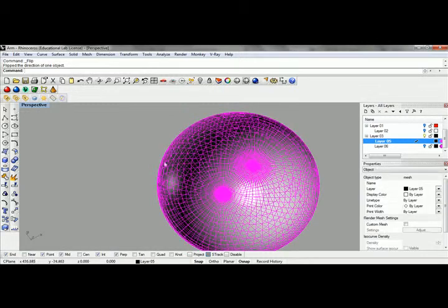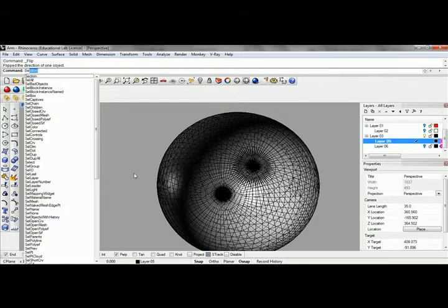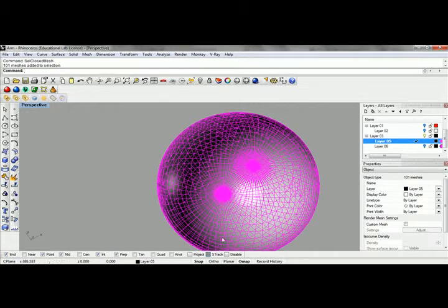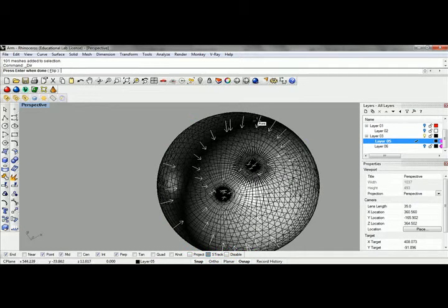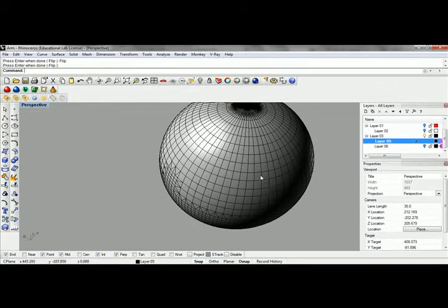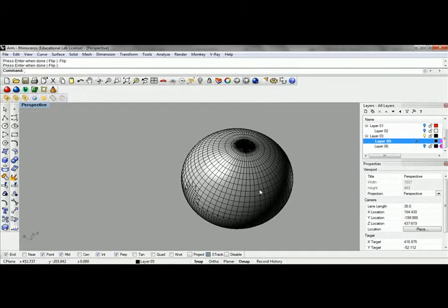So if you discover this, you want to make sure you do a visual check of these, because even if you select closed meshes, it is still selectable, but its orientation is problematic because everything is pointing in. Some of the software nowadays will actually pick that up, or give you some dark blue or dark coloring when it imports the geometry, so make sure you pay attention to that. So I flip this and hit enter. Now you can see this renders out as a nice solid object. That's something you really want to pay attention to.